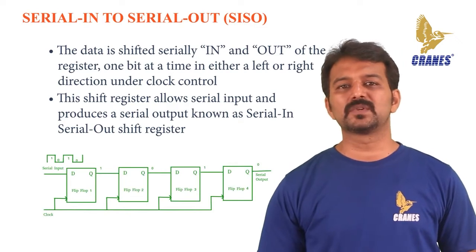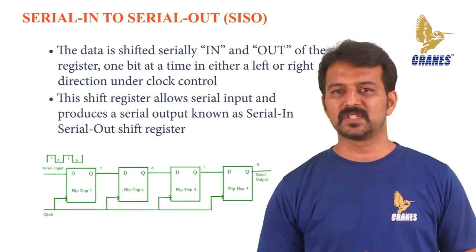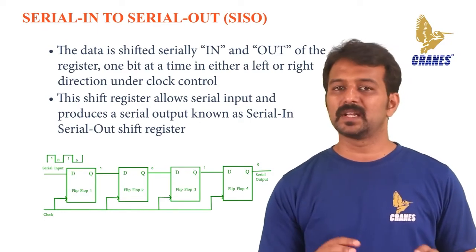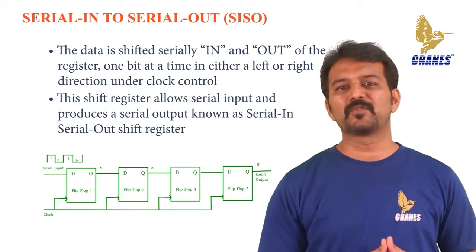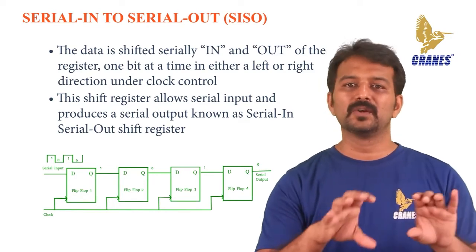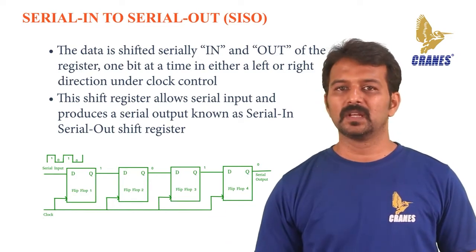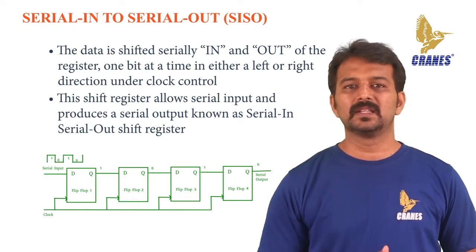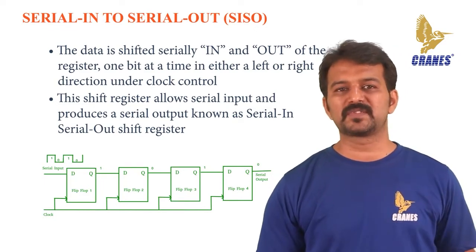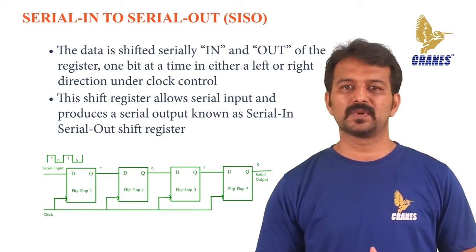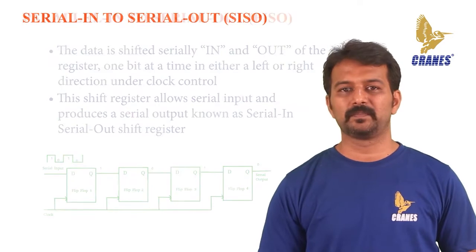The logic circuit shows a serial in, serial out shift register. The circuit consists of 4 D flip-flops which are connected in a serial manner. All these flip-flops are synchronous with each other since the same clock is being applied to each and every flip-flop. The circuit is an example of a shift right register taking the serial data input from the left side of the flip-flop. The main use of a SISO is to act as a delay element.